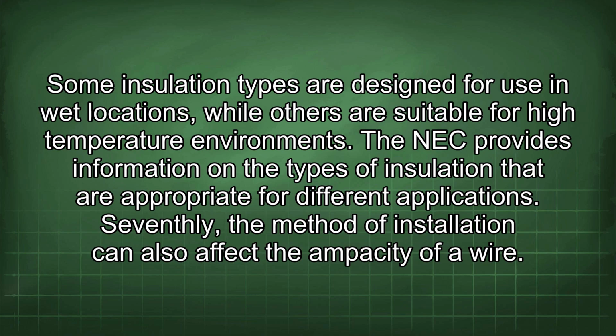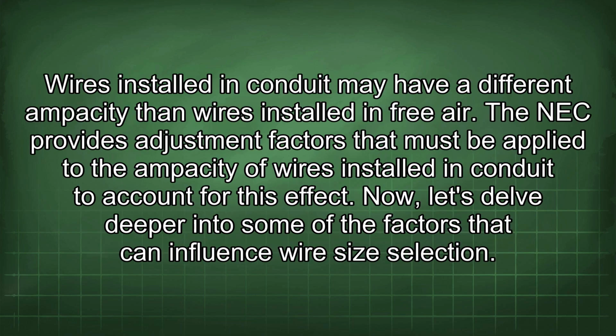Seventhly, the method of installation can also affect the ampacity of a wire. Wires installed in conduit may have a different ampacity than wires installed in free air. The NEC provides adjustment factors that must be applied to the ampacity of wires installed in conduit to account for this effect. Now let's delve deeper into some of the factors that can influence wire size selection.